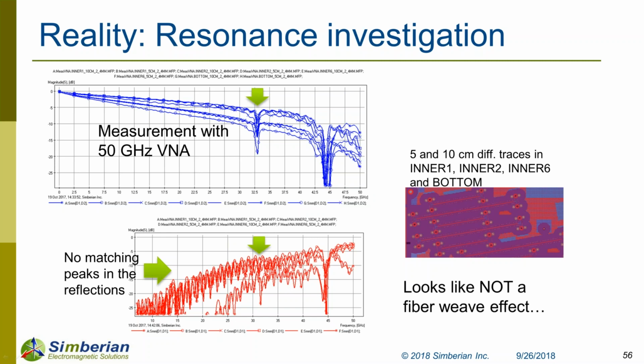And what is also interesting is to make a study where, on the same board, using blind vias, you have the upper part of the stackup with HVLP copper, and the lower part of the stackup with RTF copper, to maybe settle once and for all the question: what are the losses due to surface roughness and what are the losses due to the dielectric?